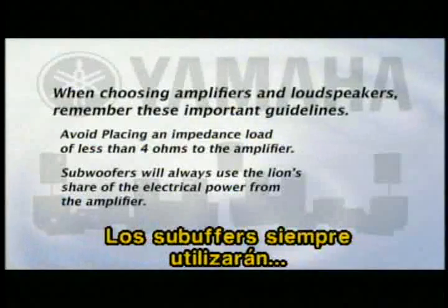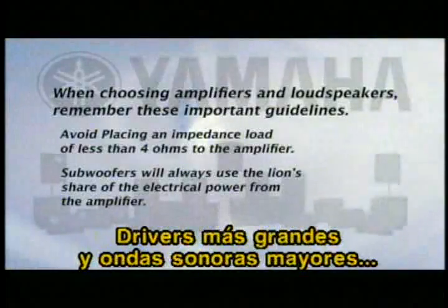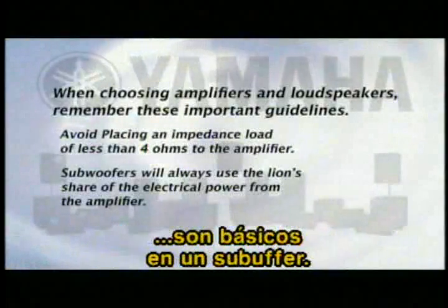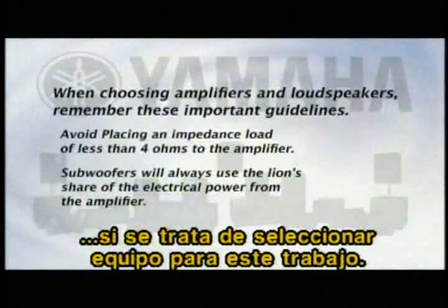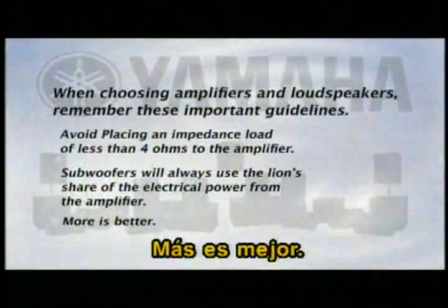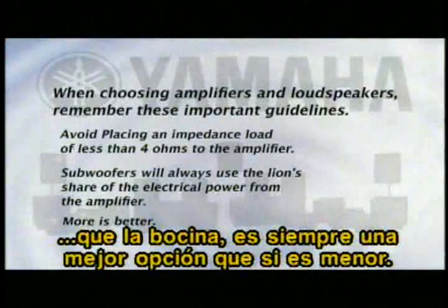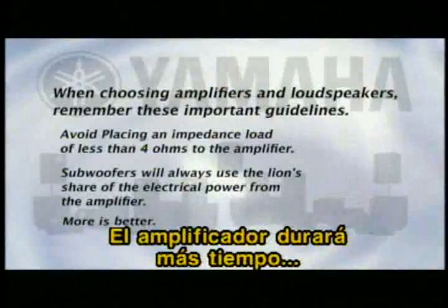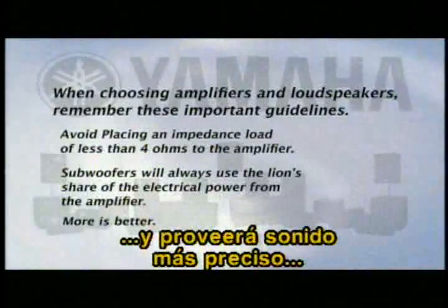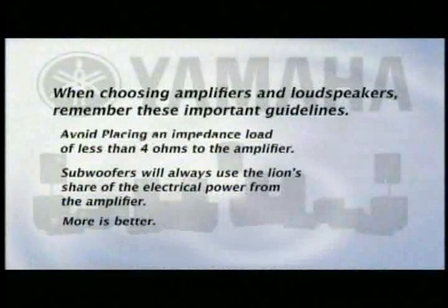Subwoofers will always use the lion's share of electrical power from the amplifier. Larger drivers and larger sound waves are the norm in subwoofers. Bigger is better when selecting a power amp for this job. More is better. An amplifier with a higher output rating than the loudspeaker is always a better choice than underpowering. The amplifier will last considerably longer and provide more accurate sound while avoiding damage to the loudspeaker.